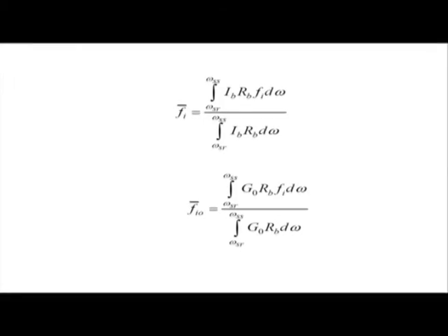And we have the argument that a significant amount of solar radiation arrives during a certain time period like 10 to 2 or 9 to 3, and the rest is only 10% or 15% of the total daily radiation. During this brighter period the clearness index is likely to be uniform, and hence we get the classical result to be quite close, even if you calculate with the data or assumed diffuse fraction and distributions.